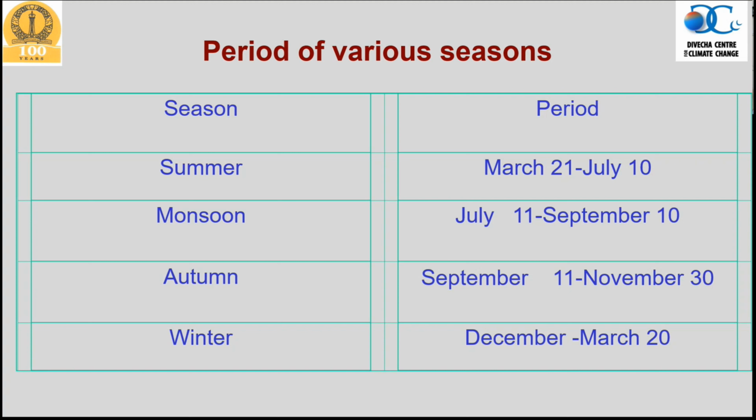These were used. Remember, these limits of seasons are derived for the Satluj River basin, including Beas and Satluj, which is the Indian part. If you go into the Karakoram, these figures are going to change. If you go to Chenab, these figures are likely to change. So you have to critically analyze the hydrograph to understand how to put the limit, so that the season is captured correctly, because there are different ways by which runoff is estimated. If you look at monsoon, it is predominantly coming because of the rain.